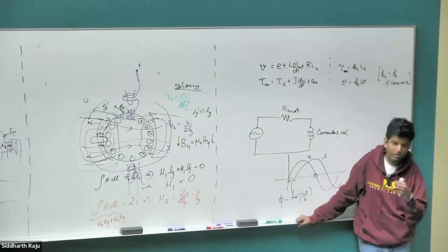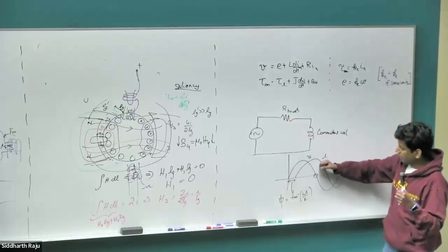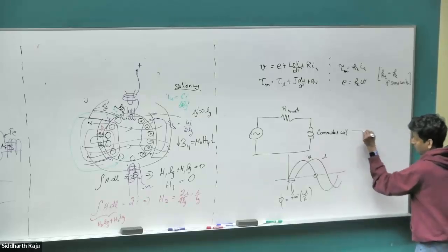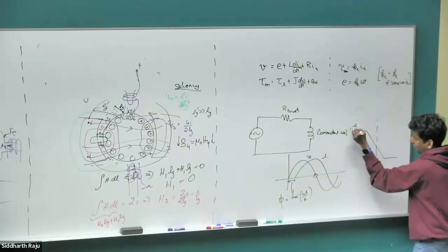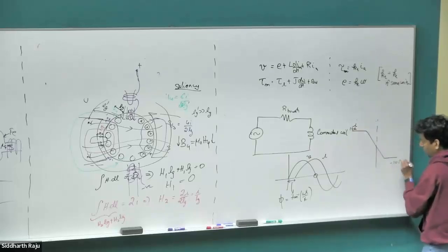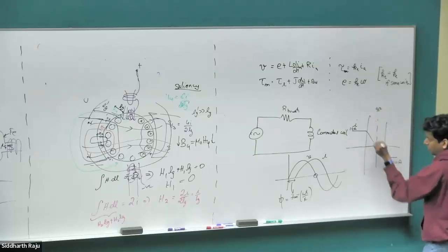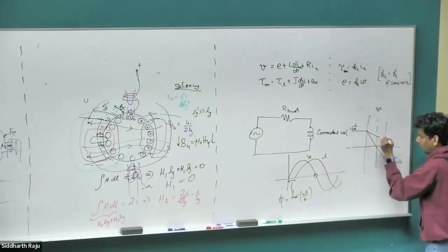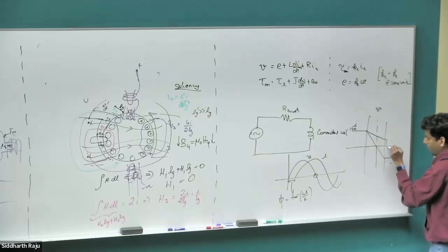There is another option as well. We can use a copper brush. But the copper brush offers very low resistance, which means that the current will be at a very large value where the voltage is at zero, and that means the commutation would be delayed. So this is what the current is going to look like. Let's say this is 10 ampere, it needs to go to negative 10 ampere once the commutation is complete. At 90 degrees, we would want it to go through zero just for the symmetry of it, right? But if this is a copper brush, this is going to take a very, very long time to decay. And it wouldn't have gone to negative 10, the current direction would not have flipped. So this part would break L di/dt, causing the arcing.